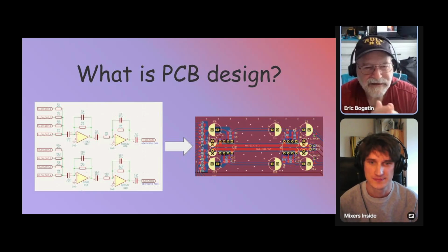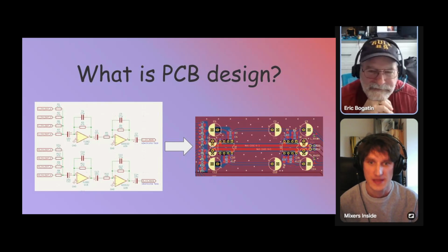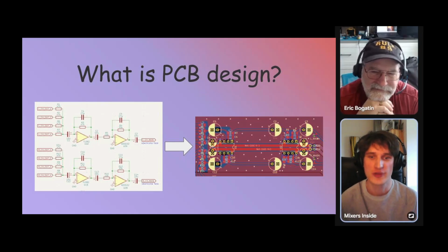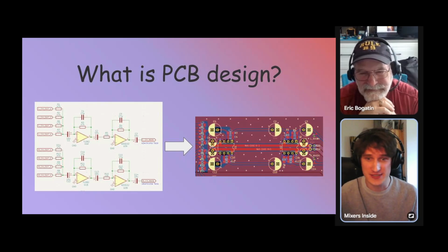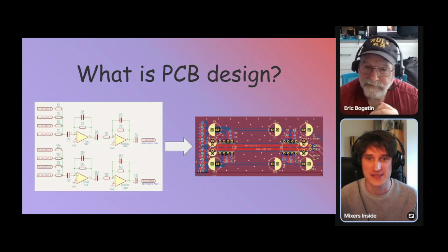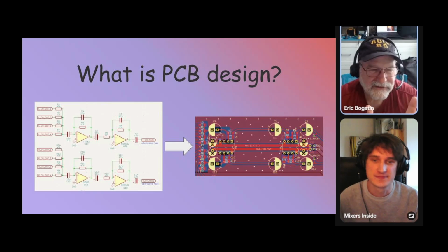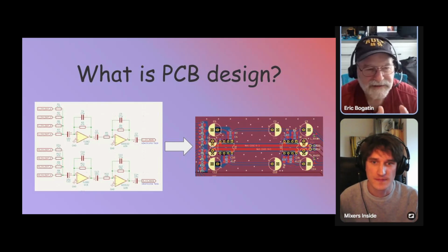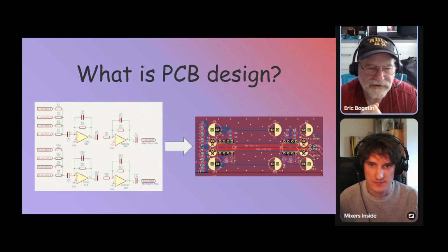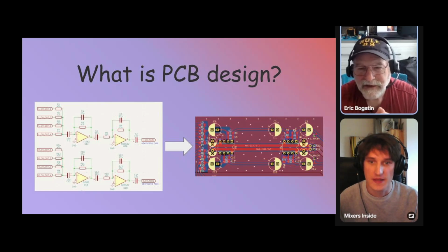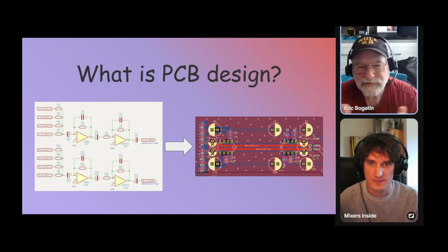The layout is where you have to start worrying about signal integrity and signal quality. Yeah, and there is really something to worry about, because when we mess up the PCB design, our circuit cannot work properly, right? There are some cases. Right. I always say that the schematic is the absolute best performance you're going to get from those components. When you turn it into the circuit board, all the interconnects are going to do is screw things up. And our job is to try to minimize how much the interconnects screw things up.